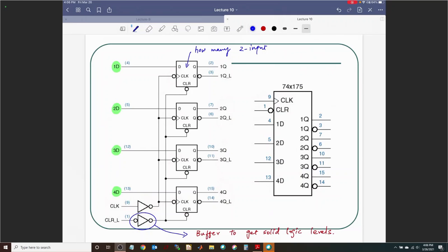This is a D flip flop. 12 was for positive edge triggered. 11. That's right. Because we can get rid of one, because now we have kind of put it over here, right? So 11 2-input NAND gates in each. So that itself makes it 44. And then you have a bunch of transistors over here. You could also use NAND gates to get those done. Alright. So the symbol and the internal design showing you all the flip-flops over there.